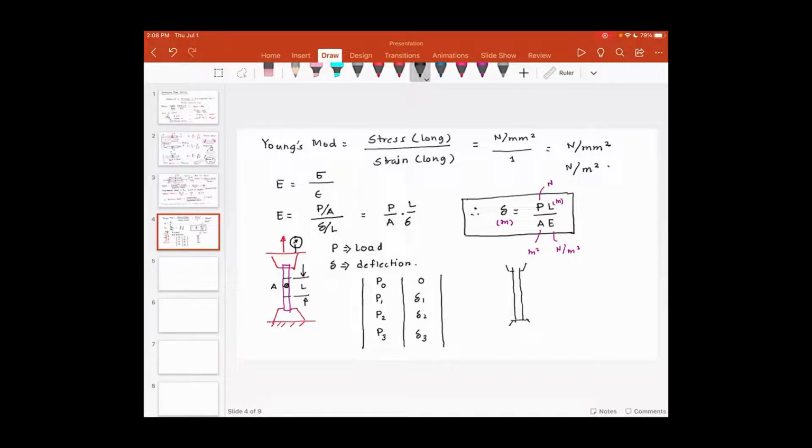So this is sort of an elastic behavior. After some time, the component gives up, and what happens is the deformation becomes sort of permanent. So you stretch the component and the component stays stretched. So it sort of reaches the plastic region.